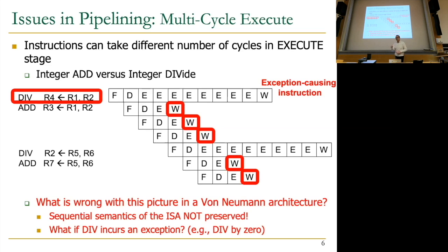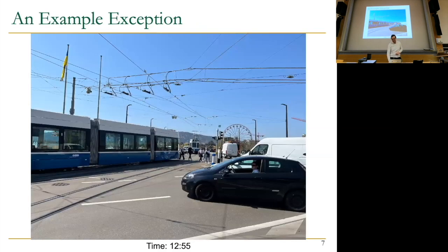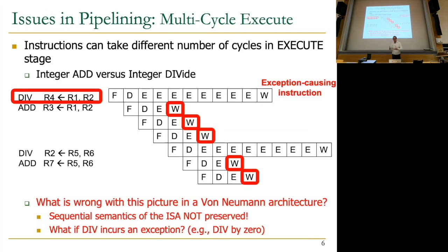But when you catch that, you don't want the later instructions to have written their values into the register file, because otherwise you'll have to be dealing with a mess. Because something is completed out of order, right? When you catch that, you really need to know what your state is in the program so that you can recover back and do something better with the program, essentially. Okay, so that's one of the major reasons why we want precise exceptions.